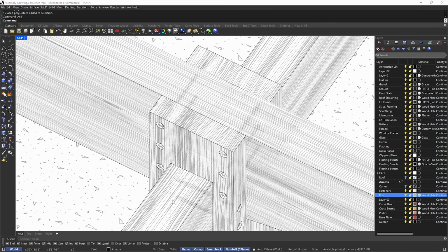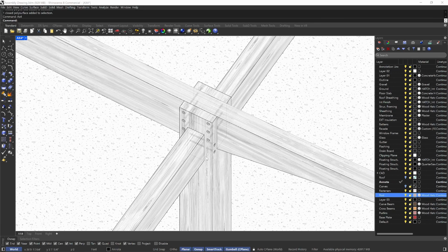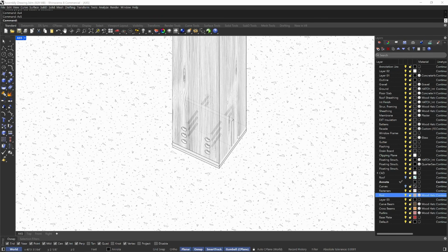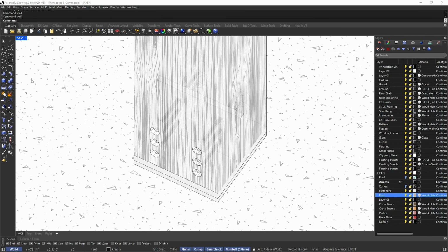You see how the material is kind of gray? That's why I do that 80%, okay? If I also go down to here for my base plate connection, this is a steel T-plate that embeds into the wood post, and that'll anchor through. So it's showing you what's going on here. Then you have your other base plate that anchors through, and I'll show you the actual exploded axonometric later. And then this is my concrete hatch. So that's basically it as a material and how you do it in Rhino, okay?